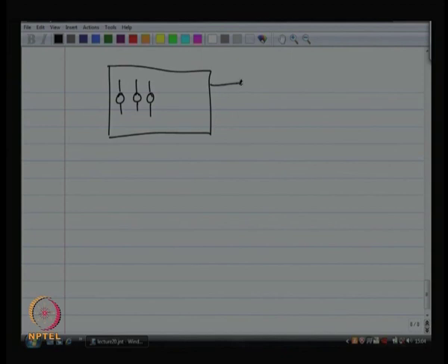Find out the mean squared noise voltage because of each individual noise source as a function of frequency. Add up all of these; you are doing superposition of a lot of different sources.